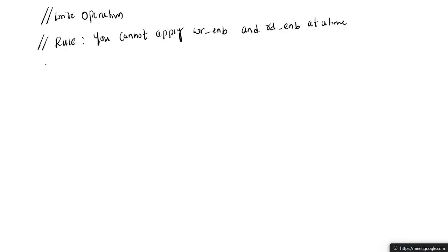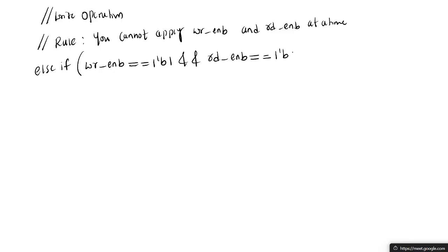So else if write_enable equal to 1'b1 and logical and read_enable equal to 1'b0, mem of write_address with non-blocking assignment gets data_in.